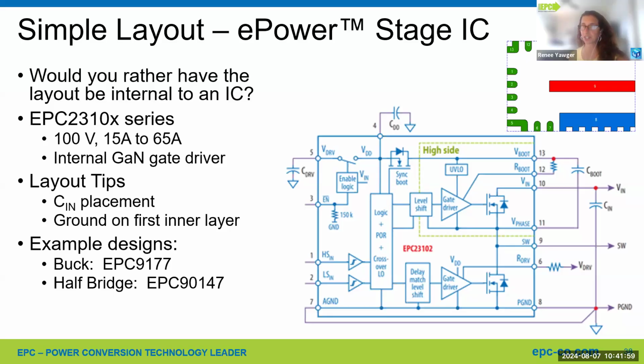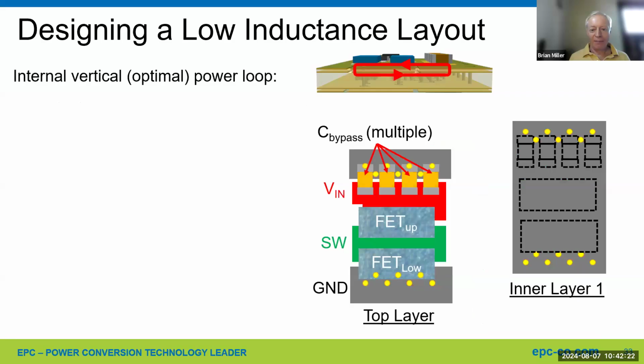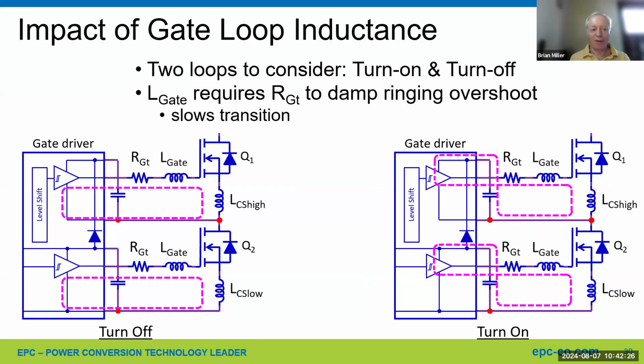While calculating efficiency of a converter, how do you measure the input power? Is it from the source display or through an oscilloscope? I think it's from the source, using a voltmeter on the voltage and a current shunt measuring the current. So the total input power going into a board. In some cases, some use the housekeeping supply as part of it, some don't.